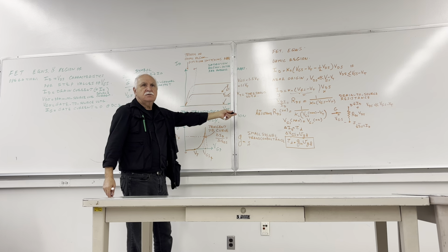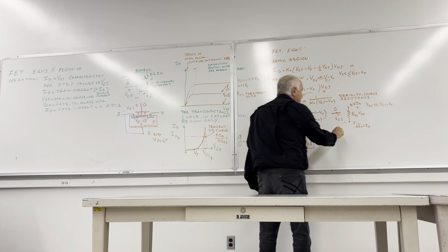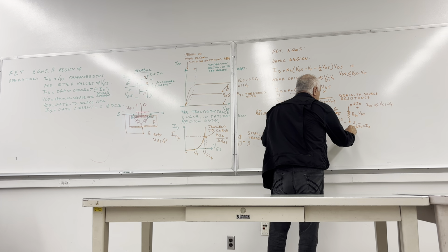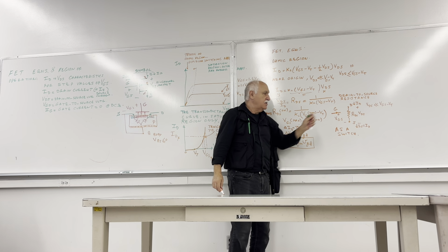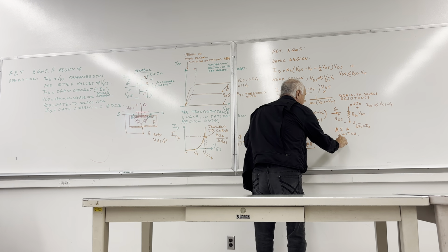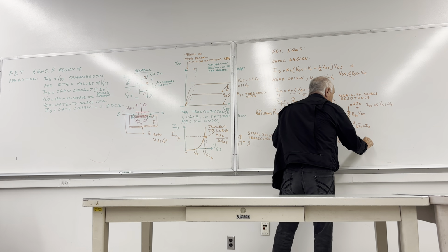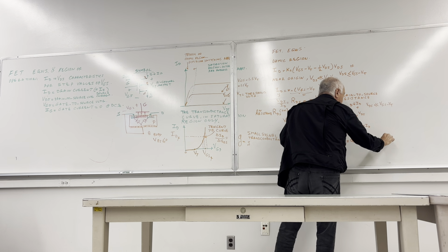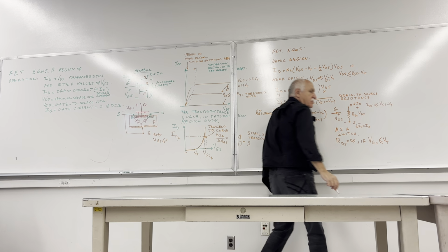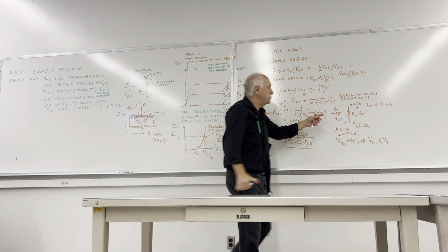Okay, so VGS on is used when the transistor is used as a switch. Automatically, this resistance will become infinity. RDS becomes infinity if VGS is less than or equal to VT. That's promised, it will happen. So if it becomes infinity, guess what will be this model?